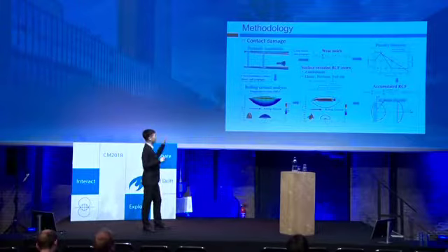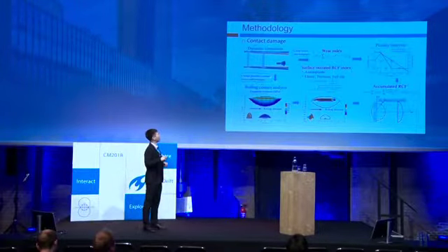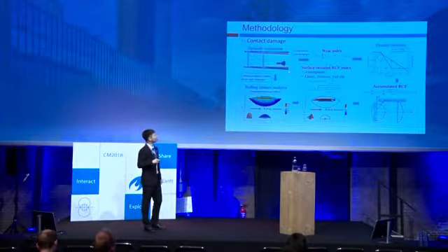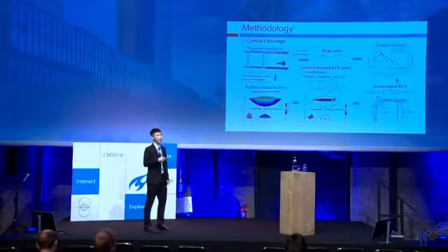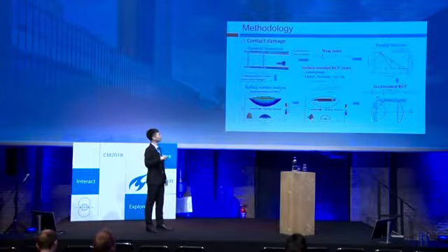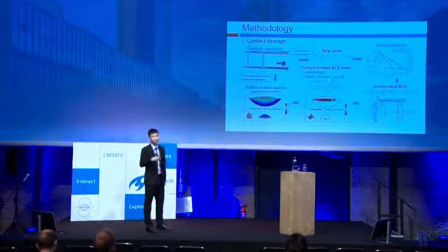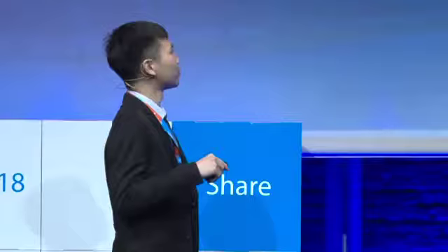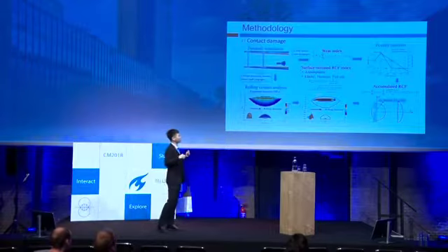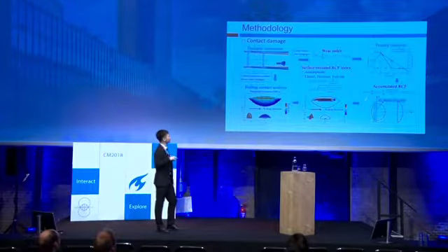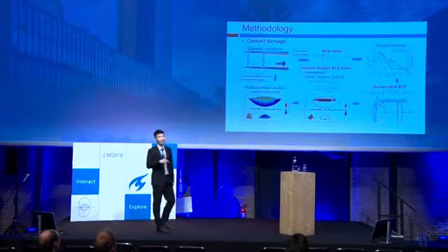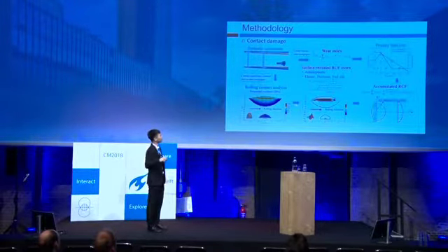After obtaining the dynamic interaction in the turnout, we calculate the wear index. Then the surface-initiated rolling contact fatigue index is evaluated too, based on 3 assumptions, including the elastic, Hertz contact, and the fluid slip. For the first one, elastic, we use the contact software to do the rolling contact analysis in the turnout area, only considering the elastic material characteristics. For the second one, the Hertz contact, it is thought that the wheel-rail contact in the center of the stripe meets the Hertz contact assumptions, and the RCF distribution is shown in this central figure.